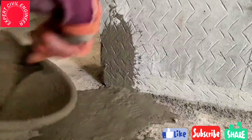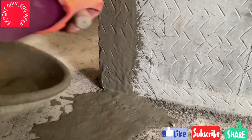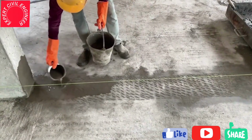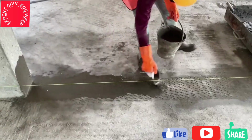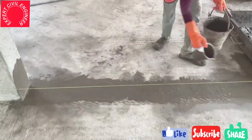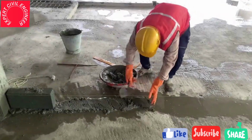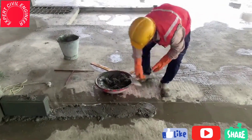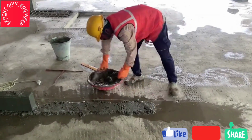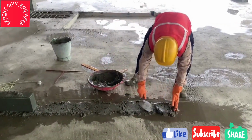A cement slurry coat of ratio 1:1 should be applied on the floor, columns and beams at surfaces where the blockwork is intended to join with structural elements. This is done to prevent moisture loss in the mortar. For the marker course, it is crucial to lay a mortar bed on the floor to achieve zero level with the thickness of 10 to 20 mm to prevent any level-related issues.